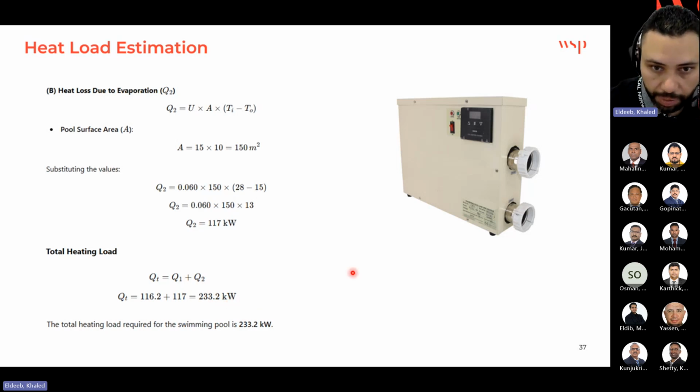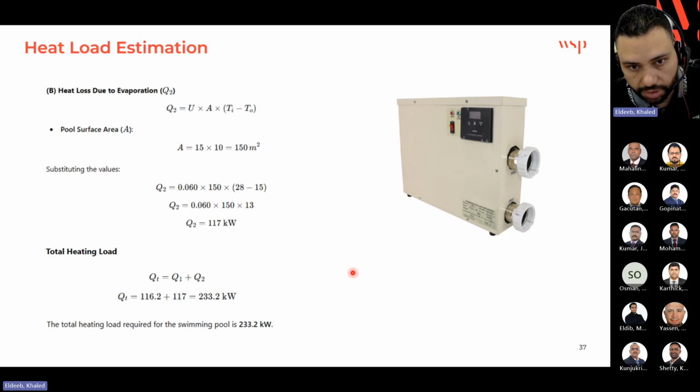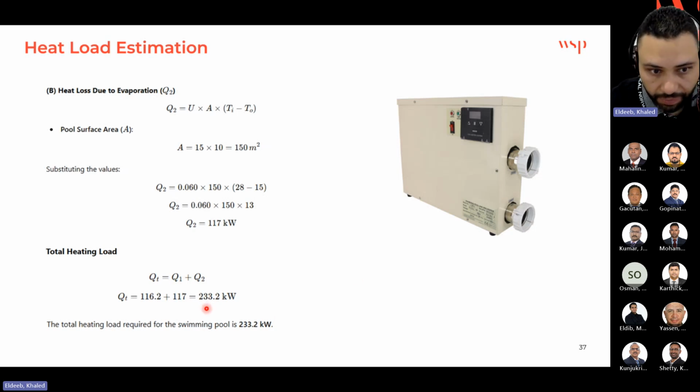If you have a heat pump, they're not using efficiency, they're using COP. So consider, like, 5 COP, which means a high efficiency heat pump. Divide this by 5, it will give you fewer kilowatts, and so on. But this is the main one. Now we learned how to do the main one.